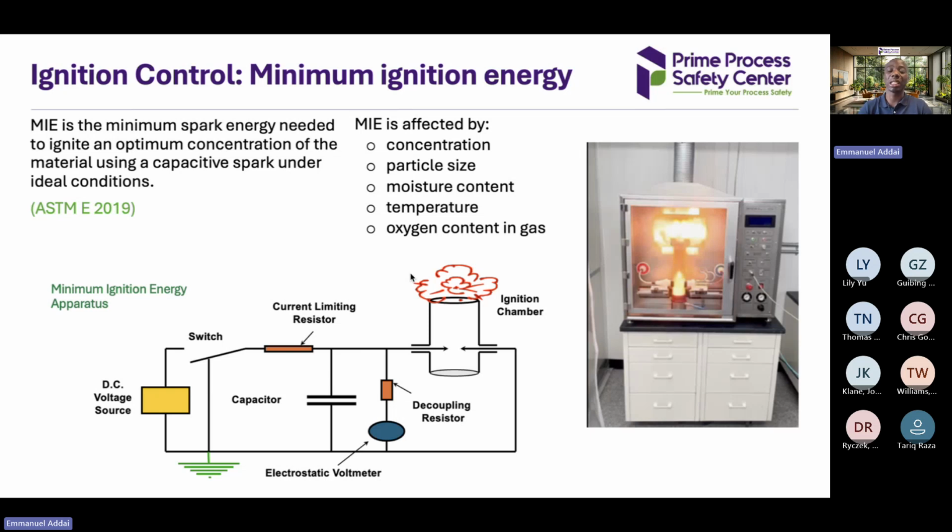Minimum ignition energy is the least amount of spark energy needed to ignite an optimum concentration. The term here is optimum concentration. The point here is that below the minimum ignition energy, we are not supposed to actually see ignition, no matter the concentration or the change in concentration.